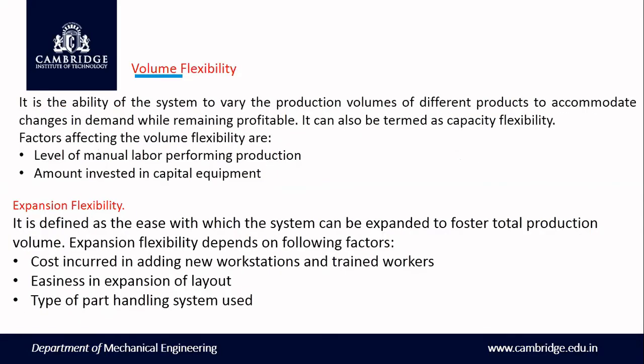And then what is volume flexibility? This is very, very important. In this, all are very important. Volume flexibility is the ability of the system to vary the production volumes. I want to produce 1,000, 2,000, 20 lakh products per week, per month, per year, that is different products, to accommodate changes in the demand while remaining profitable. It can also be termed capacity flexibility, or we can call it volume flexibility.